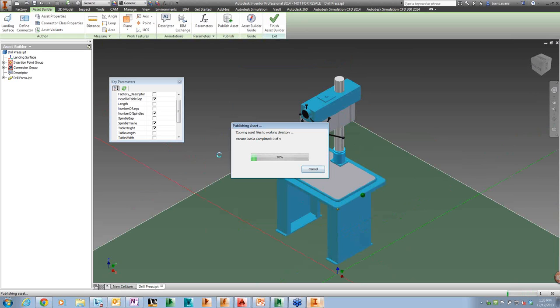So just have that information, and what it's going to do is make those updates and create that DWG. The information is going to reside both in the 3D space as well as in the 2D space over inside of AutoCAD. And really that's the connection point. Because those assets hold it together, that's how I can automatically populate that information from both a 2D perspective and a 3D perspective. And as you've seen, I'm not limited to what's inside the box. What comes with Factory Design Suite, I can also take that information and add to it. I don't have to use assets, so we highlighted that workflow as well.